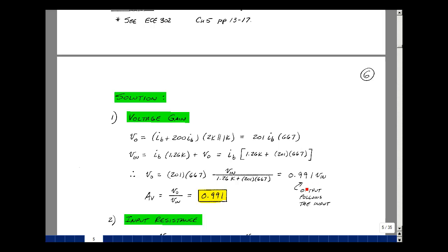For this particular amplifier, the voltage gain is actually never greater than 1. It's always less than or equal to 1. In terms of an amplifier, I'm not getting any voltage increase, but hopefully I'll get a current increase. The reason this turns out this way is that the term here in the denominator is also in the numerator, and there's also a term added, which is that resistor labeled R pi. So this is one of the disadvantages of this amplifier. I can't get a voltage gain out of it. The circuit is sometimes called a voltage follower in that the output follows the input.